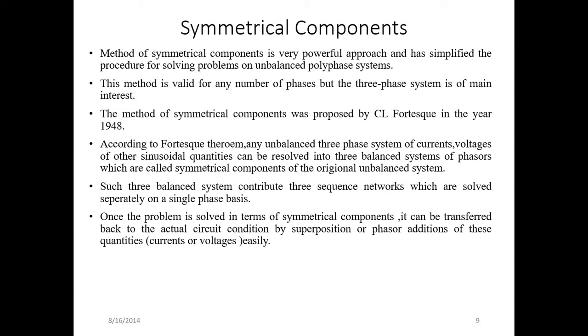If we are interested in the definition of the symmetrical component, according to the Fortescue theorem, any unbalanced three-phase system of currents, voltages or other sinusoidal quantities can be resolved into three balanced systems of phasors, which are called the symmetrical components of the original unbalanced system. Such three balanced systems constitute three sequence networks, which are solved separately on a single phase basis.